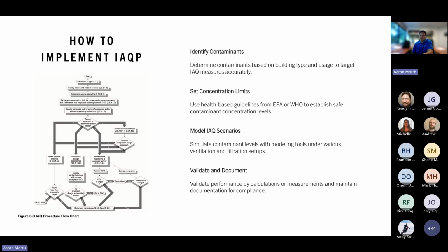So maybe some ozone or something you might want to treat, but you'd be able to lower that ventilation rate and therefore increase the efficiency of that system by using the IAQP, similar to maybe a conditioned self-storage unit, where you're not really going to have occupants in that space, right? And that would be different than a gymnasium where you will at times have full occupancy and have a large ventilation requirement, and maybe you use that with a demand controlled ventilation strategy. But you could otherwise use IAQP in that gymnasium to reduce your minimum ventilation rate.